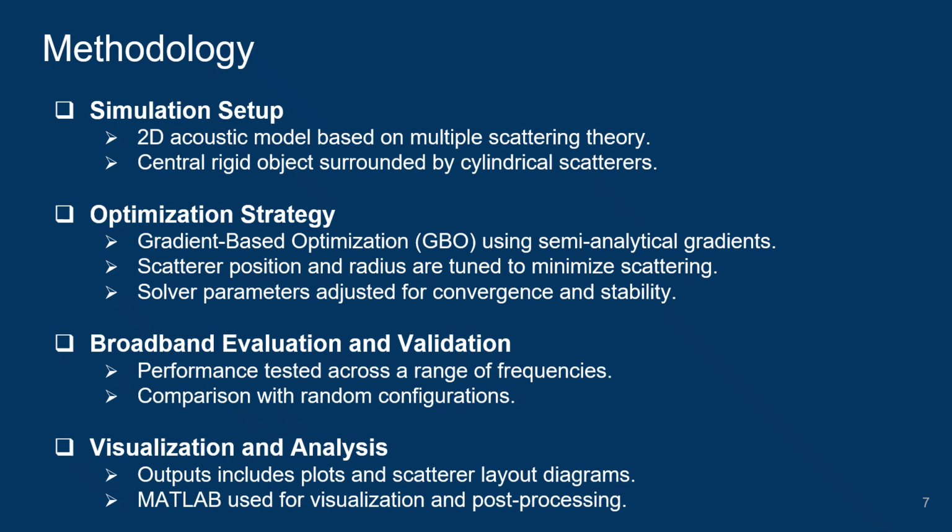Methodology starts with simulation setup. A 2D acoustic model based on multiple scattering theory is developed, in which a center rigid object is surrounded by cylindrical scatterers. Gradient-based optimization is used to adjust the position and radius of scatterers for minimizing scattering.